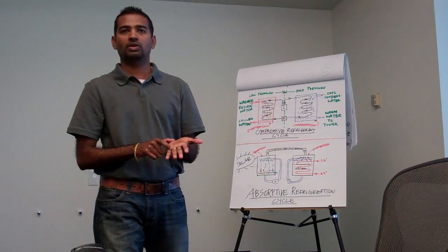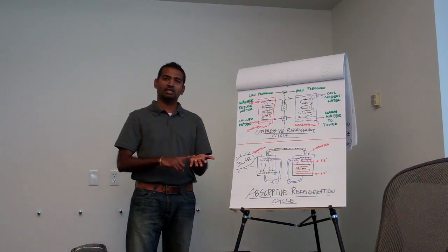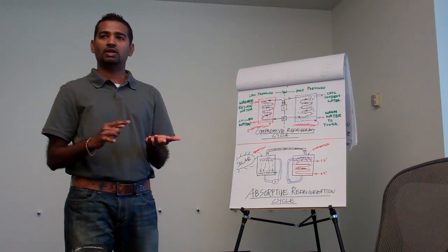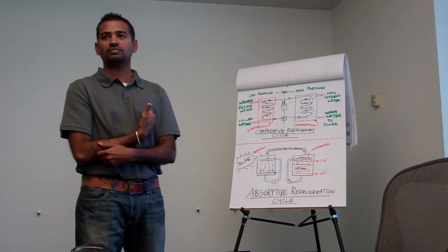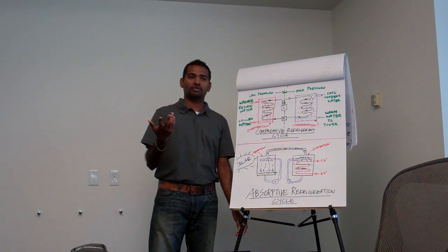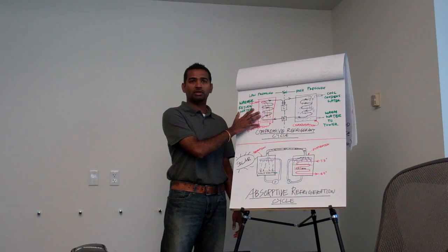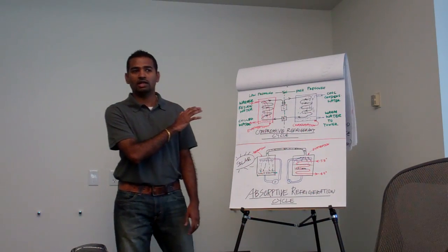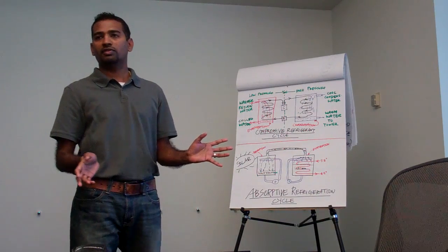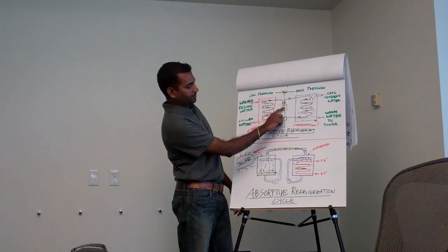The next version of HCFC, hydrochlorofluorocarbons, that's the one that we are using, is HFC, hydrofluorocarbons, and then the last and the super version is the hydrocarbon. But the problem with the hydrocarbons is flammability. So it is important to know which type of refrigerants we're using in our projects too. It's not only on HVAC design and equipment, but it's also on refrigeration, anywhere refrigerant is used.